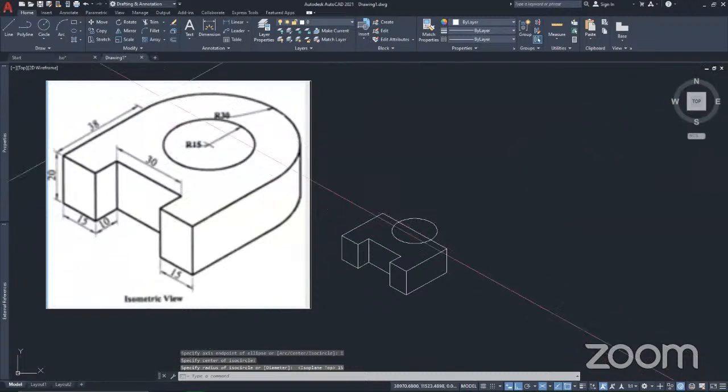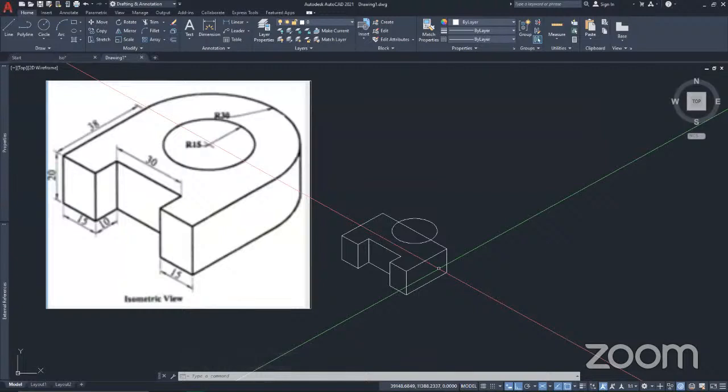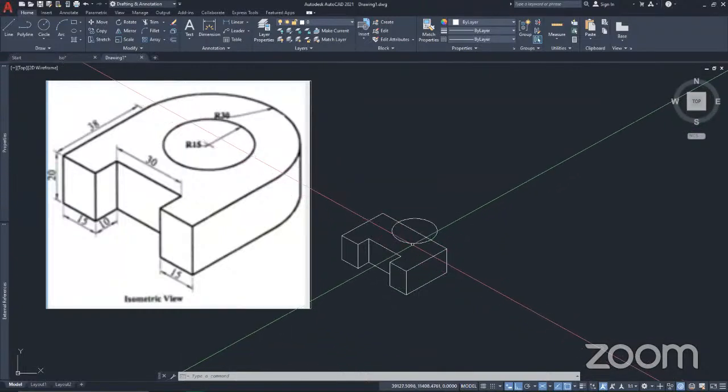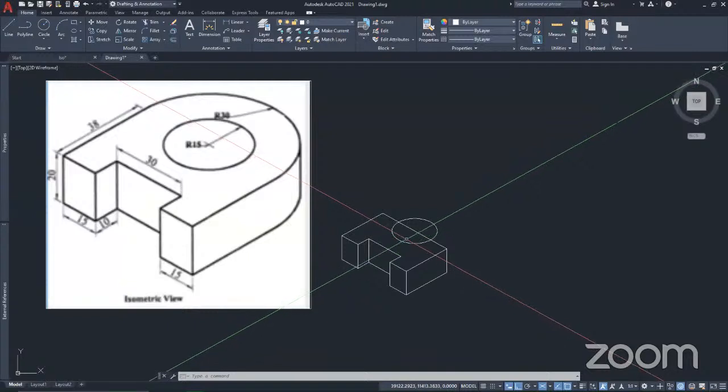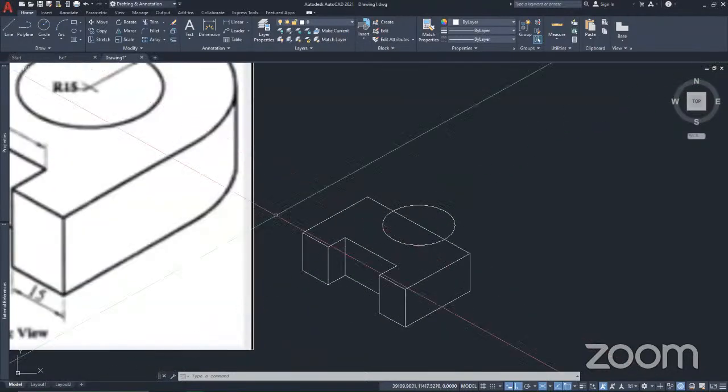After that, we need this other one that is an arc. And you have several ways to do this. You can use the ISO circle, you can use elliptical arc. So in this case, let's use the ISO circle. Just go ahead, same option, the same process. Do this and select the center of the circle.